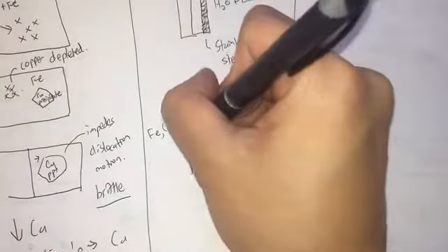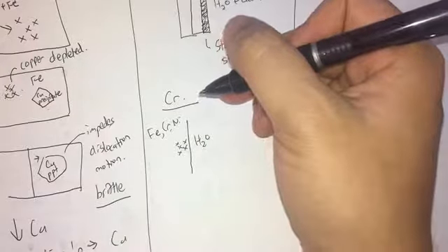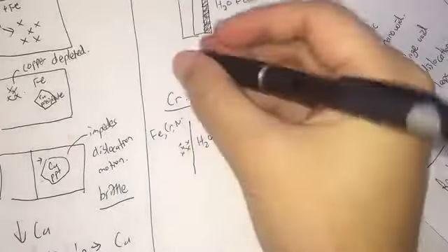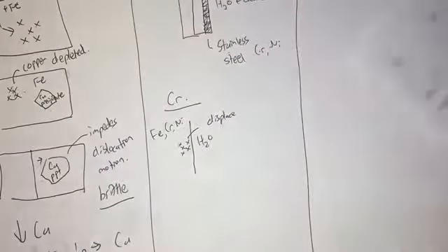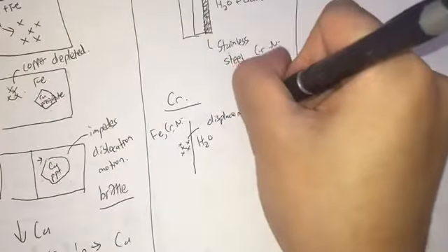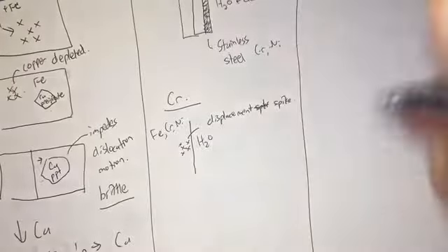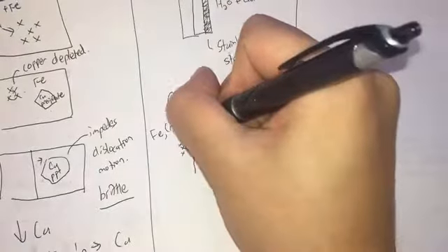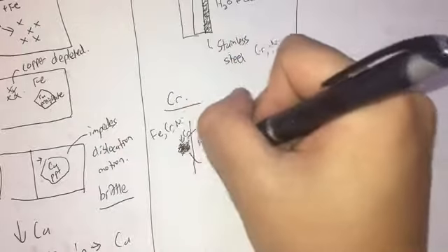But let's say you have a high vacancy concentration here caused by a displacement spike. Say you have a displacement spike here, caused by none other than our neutron damage. So there's a high concentration of vacancies here. What happens is that this tends to pull chromium towards here to form a chromium carbon precipitate.